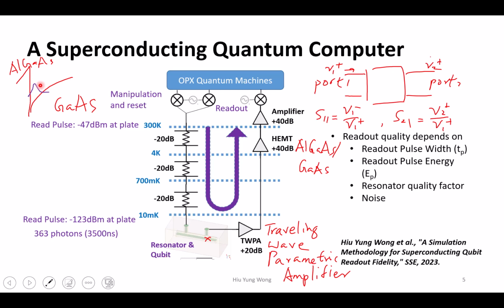When we talk about the quantum dot, we say that this helps us to confine the electron in one direction, right? If you forgot, this is into the wafer, this direction, right? Into the wafer, or into the chip. And then you can add other gates to confine another two directions, then you get a quantum dot. Don't know if you can envisage this. I don't have a picture here.